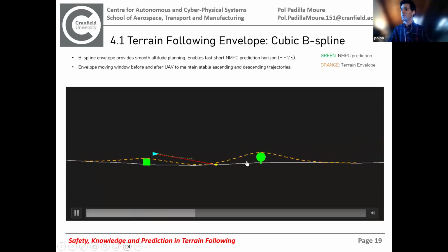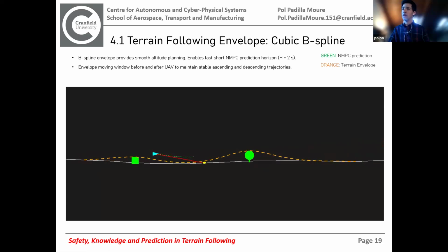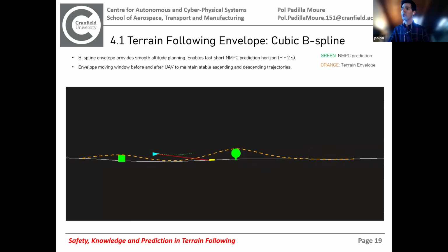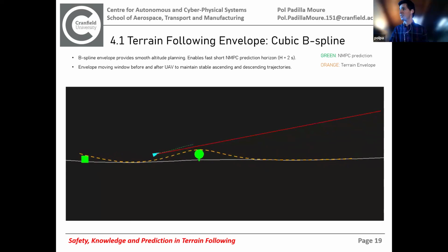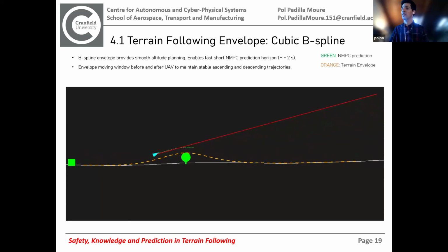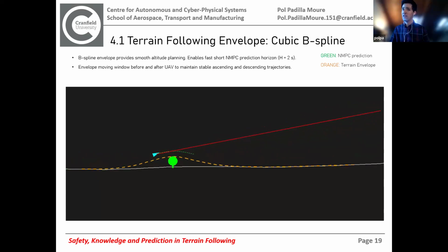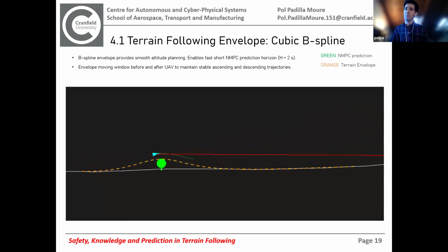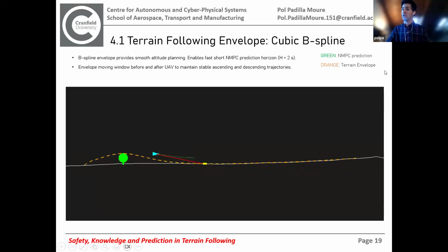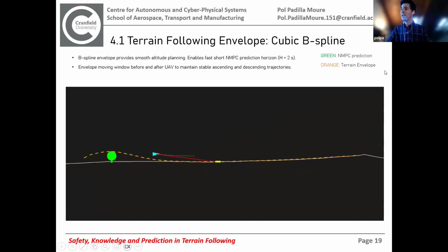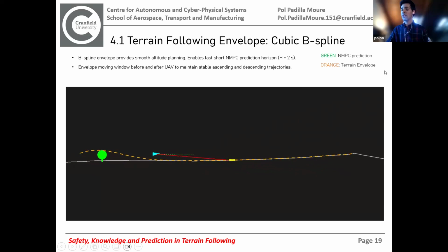So dividing this problem into 2 stages, we are actually taking advantage of what can be quickly computed and fusing the data, and then just using the MPC for a single task, that is the guidance and control of the aircraft, not combining data and obstacles at the same time. And just using the same MPC parameters as before, we are getting a much better performance without any non-convergence failure of our solvers.